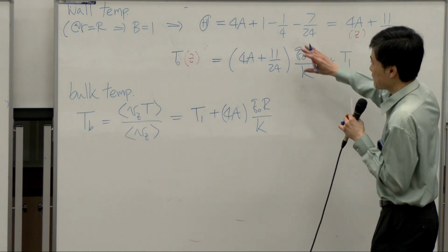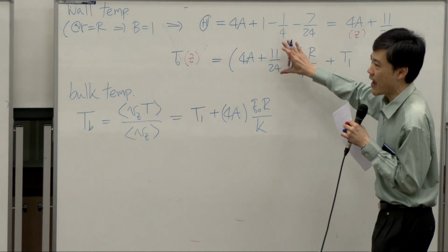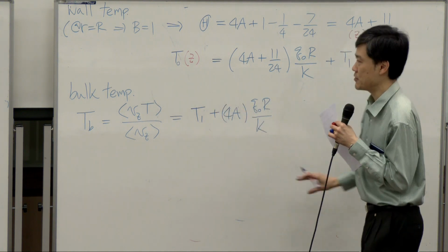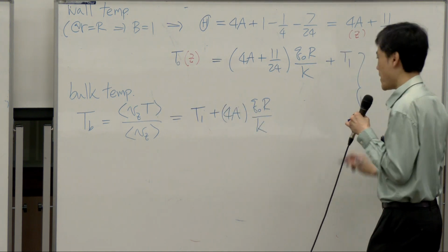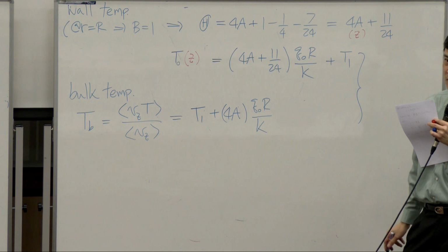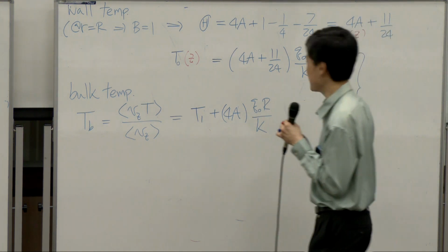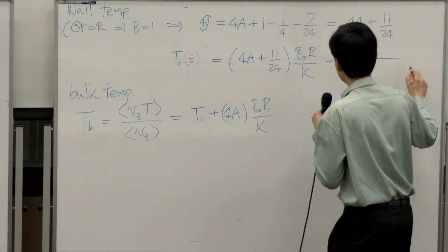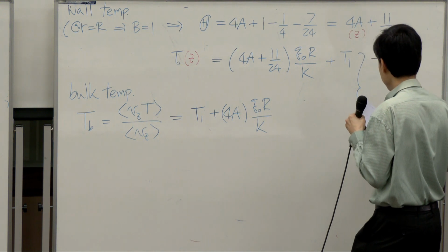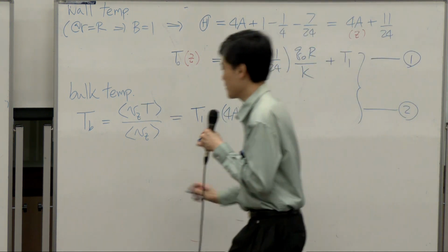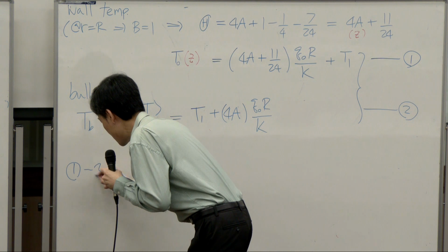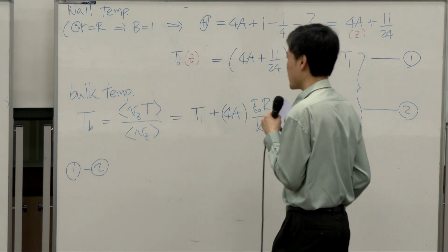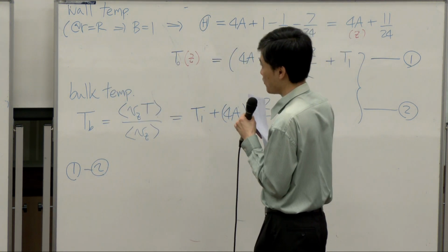Now, once we have wall temperature, which is higher than bulk temperature, if I take this pair, that's my driving force. Okay? So I take the first equation minus the second equation. That is my driving force for heat transfer locally.